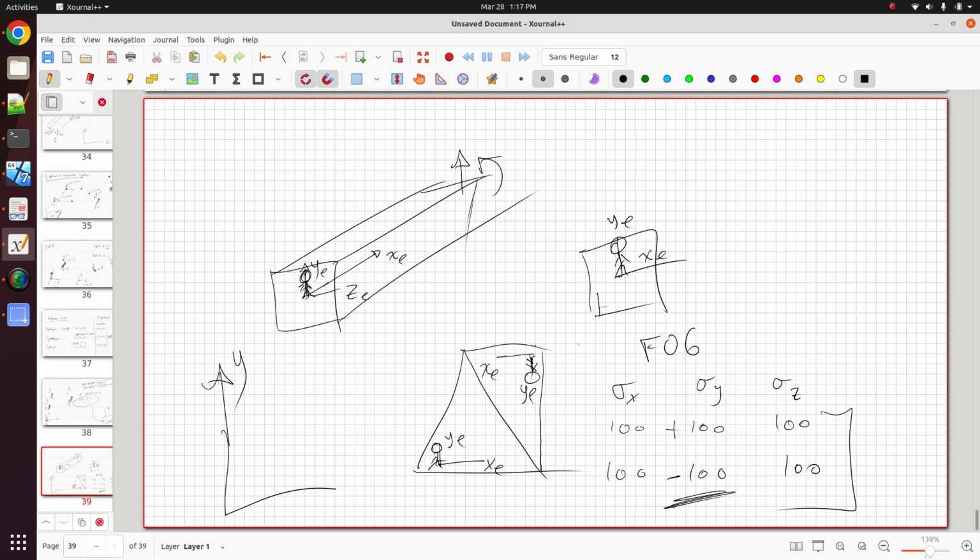So for me, when I was learning Nastran coordinate systems, I always think of that stick figure. What does the observer's position and orientation look like? Am I looking at the results at a grid? Is the grid in a cylindrical coordinate system? Is it in spherical? If I'm looking at beam results, what does that observer look like? If I'm looking at the results of 2D elements like a C quad or a C tria 3 or 6, what do the observers look like there?